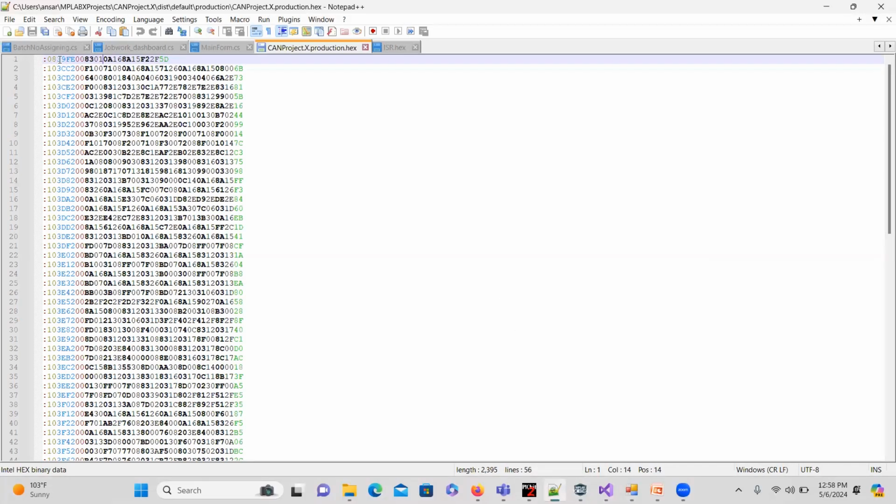See here, it starts from 39FE. So it is their interpretation. But when I flash and see the address in the memory of the microcontroller, they start from the address that I created the offset. From there only, it is flashed.